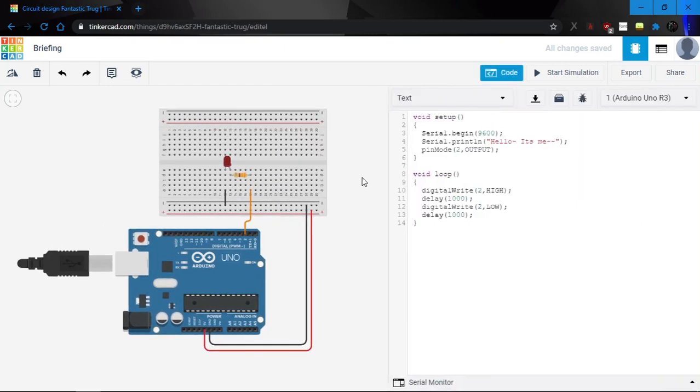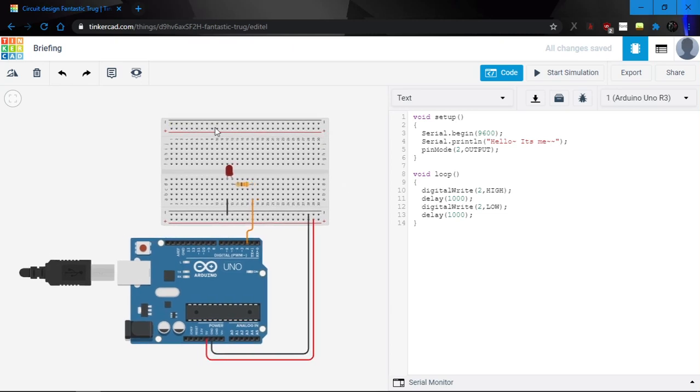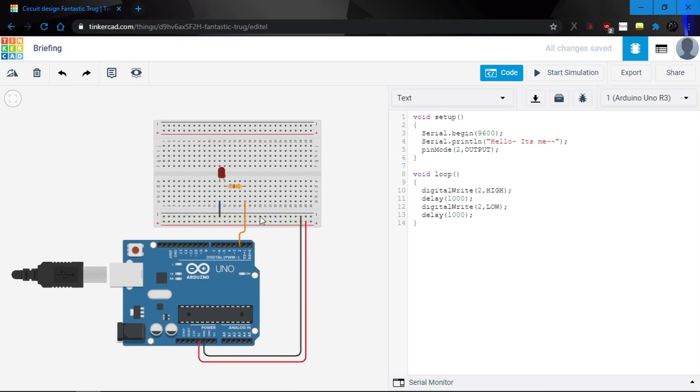Another thing that you need to make sure of when you do a project, either in simulation or in real life, is that there is no short circuit, which is 5V and ground connected directly, or it will damage your components. In the TinkerCAD simulation, if you make electronic errors, such as a short or wrong pin connections, no error will be shown here. But if you make programming errors like a missing semicolon or wrong words, it will display errors here. During this hands-on session, you will learn a lot about how you can use the Arduino IDE to program other electronic components.